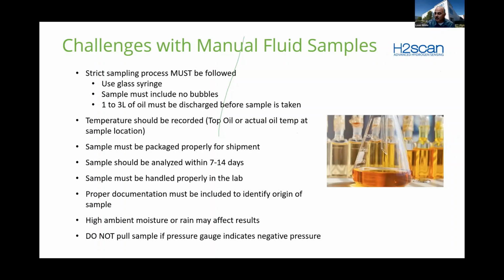the transformer. So I was at a power plant in Texas one time, and a customer said, in the winter, we open the valves on these transformers and the oil doesn't come out. We don't understand why. I looked up at the pressure gauge and I said, you need to add some nitrogen pressure to that transformer, and you should not be opening those valves when the transformers are in negative pressure. So these are real things that happen, and proper training, of course, is very important.